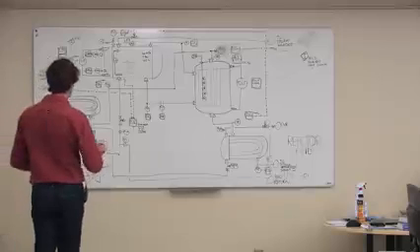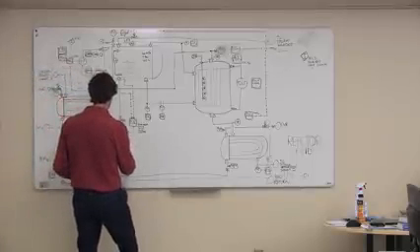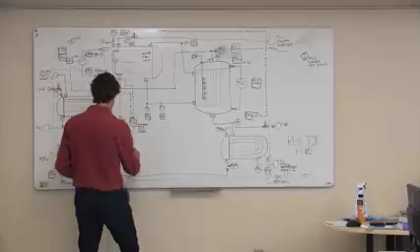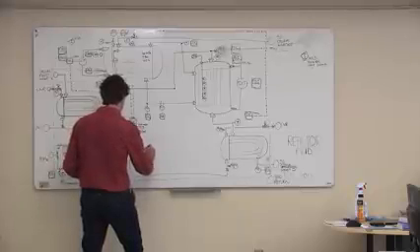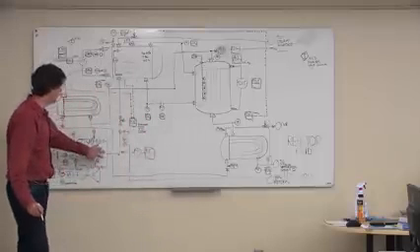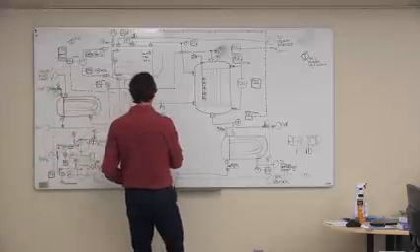Here's one thing that I would be interested in knowing: how much pressure those pumps are putting out. So I would put a pressure transmitter on there, so that if the pumps for some reason are not putting enough pressure out, we could be alarming on that, and we could be thinking about shutting the reactor down.